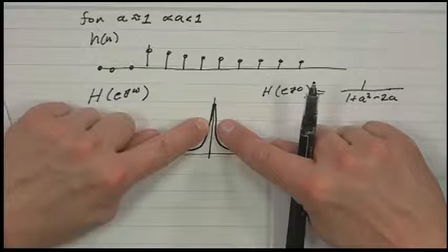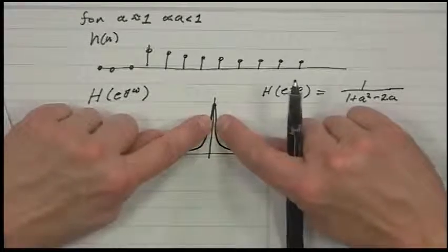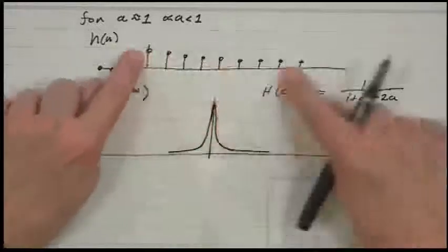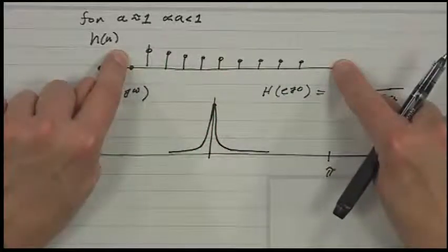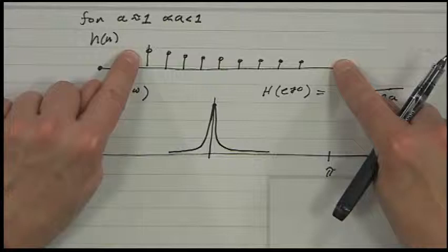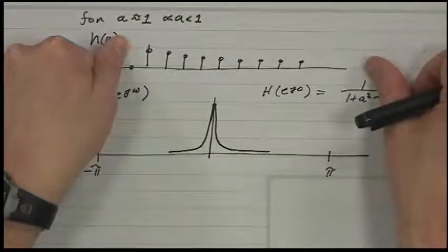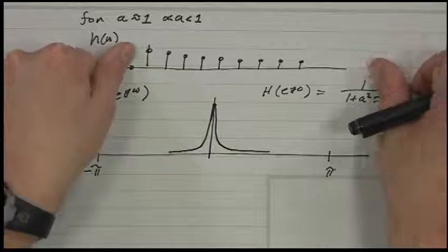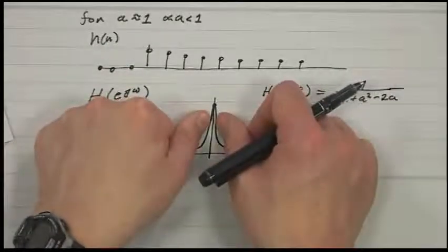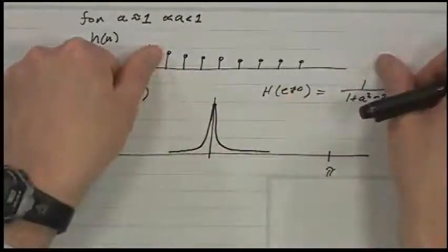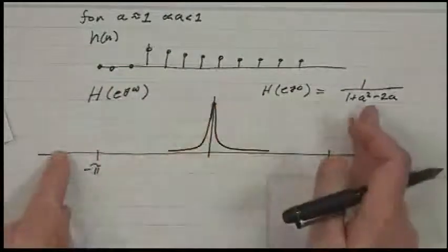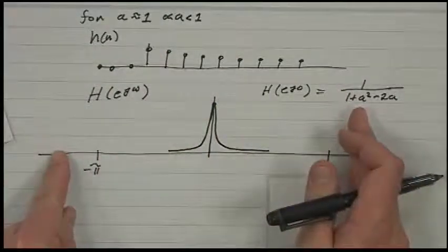So this is small in this dimension, so it's got a very long impulse response. If I wanted to implement this as an FIR filter, I'd have to take a very large window to get a good approximation, because the structure in frequency is very fine. So a larger window in time gives me finer sampling in frequency, is one way of thinking about it.